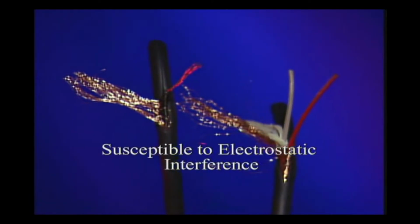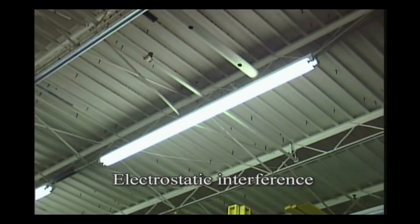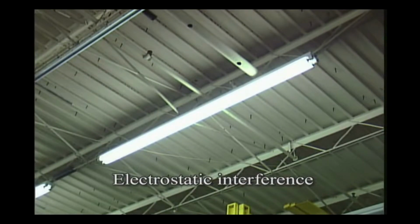First, unbalanced mic lines are typically terminated into extremely high impedance, and the higher the impedance, the more susceptible to electrostatic interference. If you've ever turned on a fluorescent light and heard the buzz it produces, you've heard electrostatic interference. Like fluorescent lights, electrostatic interference can manifest itself as an audible buzz in the output sound.